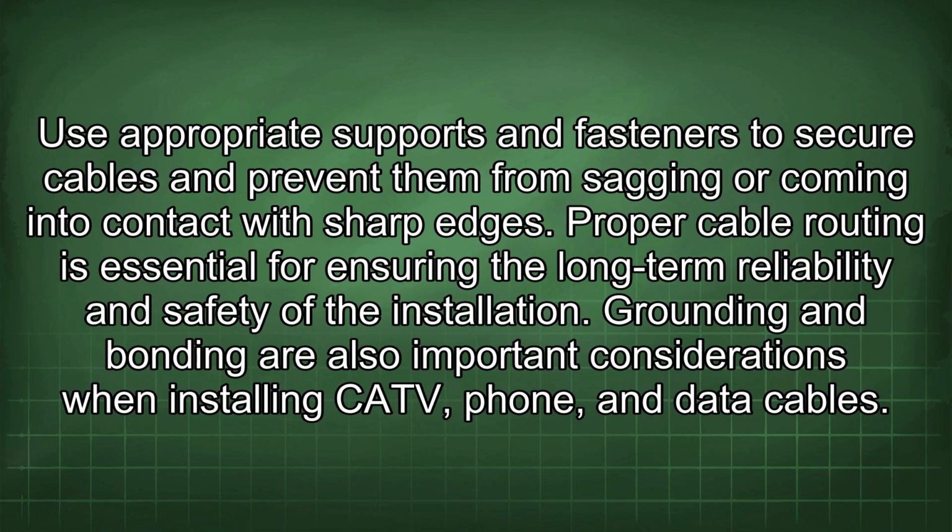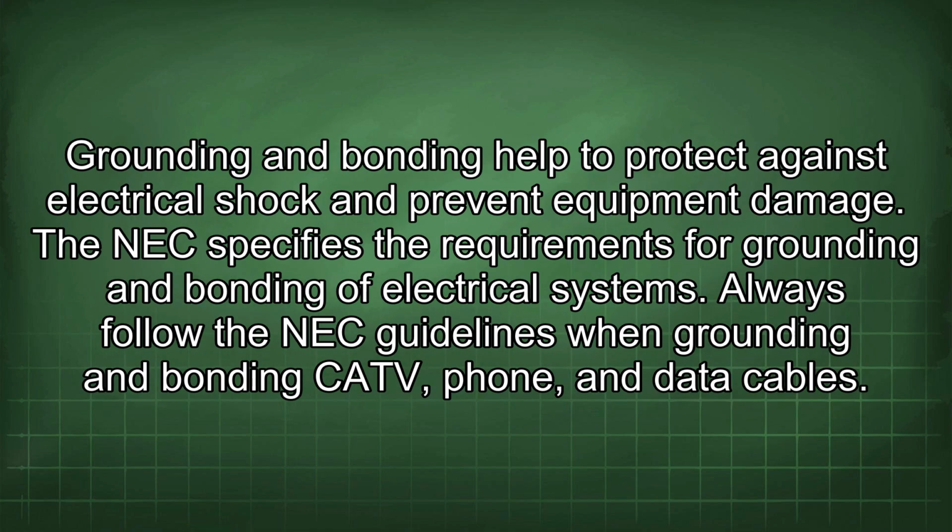Grounding and bonding are also important considerations when installing CATV, phone, and data cables. Grounding and bonding help to protect against electrical shock and prevent equipment damage. The NEC specifies the requirements for grounding and bonding of electrical systems. Always follow the NEC guidelines when grounding and bonding CATV, phone, and data cables.